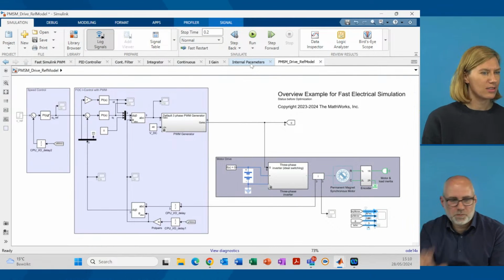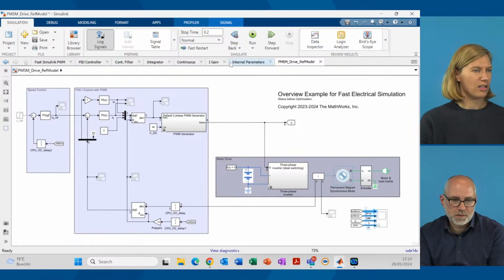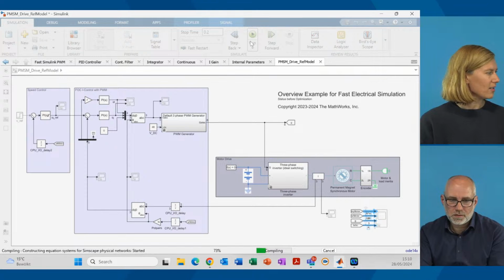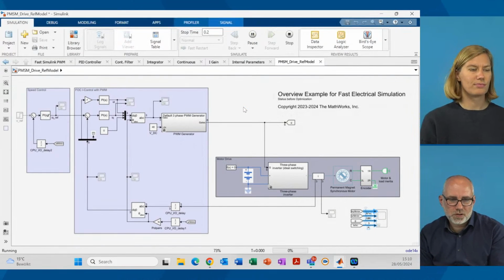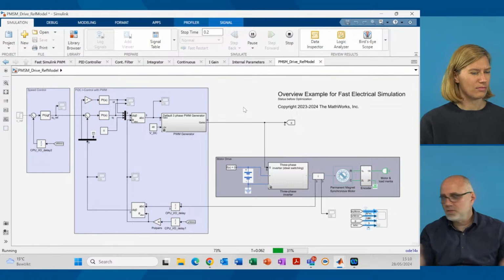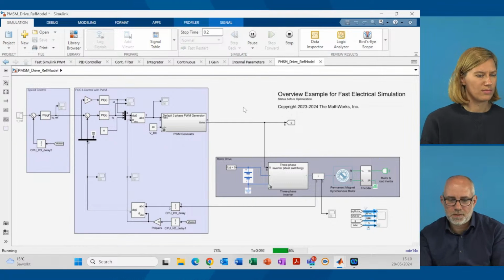And we're a little bit limited with the monitor here. So let's repeat the simulation. I don't do it from the Simulink profiler any longer. I just run it here. We had, I think, 44 seconds. Yeah, so overall it was 49 seconds, I guess. And 44 the execution, the runtime. And of course, if a simulation takes longer than 0.2 seconds, which is the stop time at the moment, only the execution time will expand and not the initialization time.